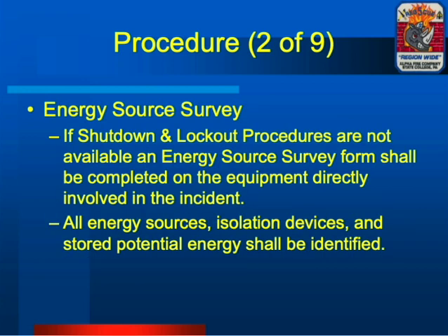Then we're going to start our energy source survey. So this is where we're going to use our paperwork, and I'm going to go over that in a few moments. We're going to work down through the survey, and all the survey is really giving you is a check sheet of things to look for, whether it's yes or no, does it apply to what we're working with, does it not apply, but it's really just a guide for working through how to limit or shut off the energy sources used within that facility or within that area of operation.